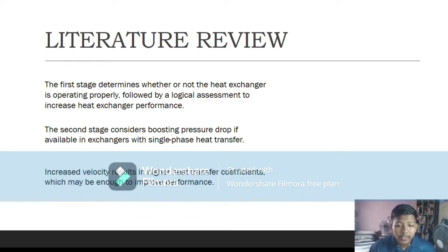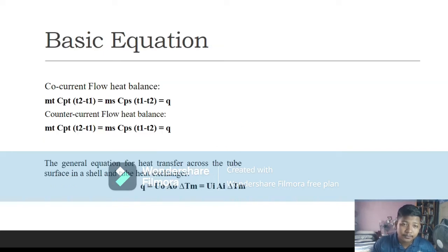And following that, the expected fouling factor should be carefully evaluated, and heat exchanger performance can be improved with regular cleaning and less conservative fouling factors. Finally, fin tube inserts, twisted tubes and redesigned baffles may be used in specific cases to optimize heat transfer.